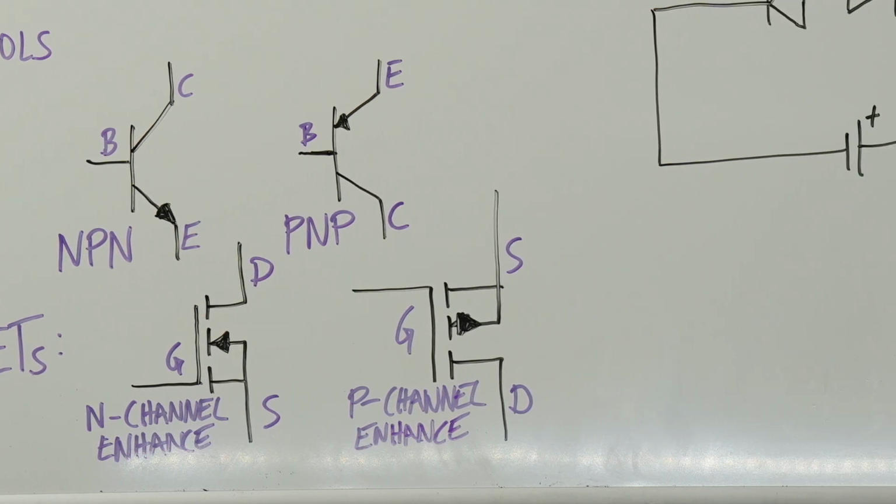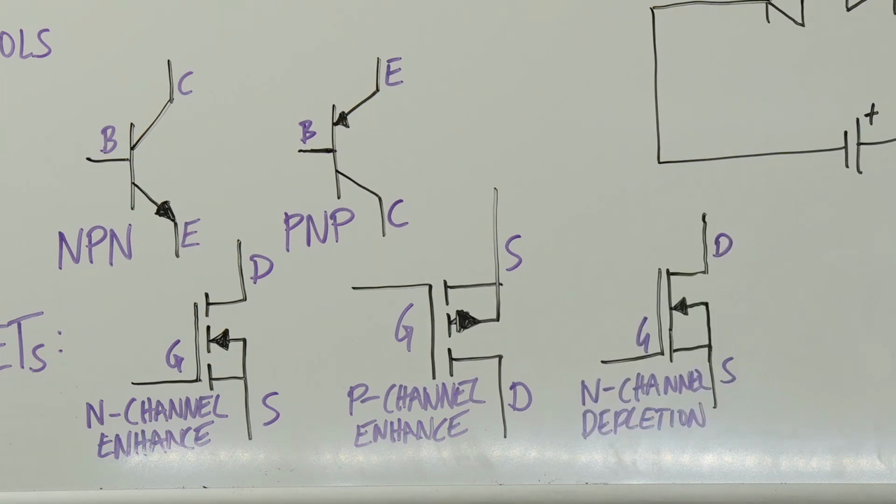In all cases, the third pin on the right side of the symbol represents the connection between the substrate and the source. For depletion type MOSFETs, the three terminals on the right hand side are connected, indicating the pre-manufactured terminal. The letters S, D, and G represent the source, drain, and gate terminals of MOSFETs respectively.